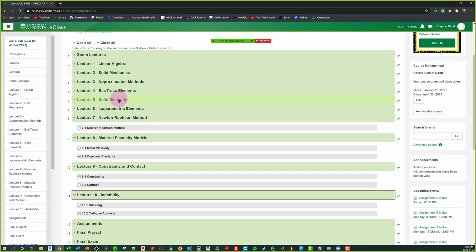When we deal with beam elements and when we deal with shell elements, they have that rotational degree of freedom, and that adds a lot of complexity into our theoretical formulations. Those are actually C1 continuous, which means that not only is the displacement continuous, but the rotation field also has to be continuous. Therefore, the formulations of those elements get a little bit messy. So those are formulations that I'm going to show you guys in lecture 11, but it won't be covered on the final exam, anything like that. So just something to be aware of.